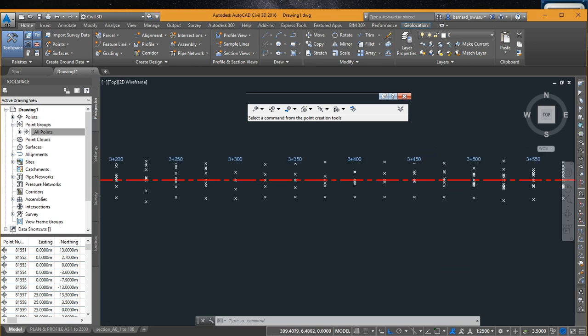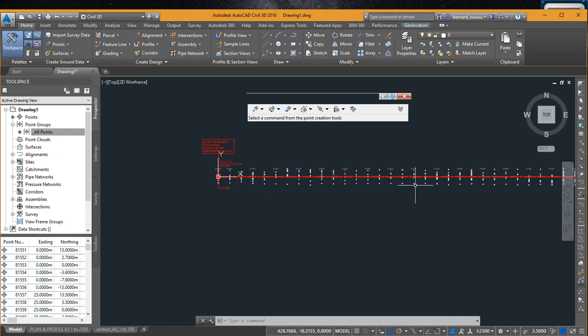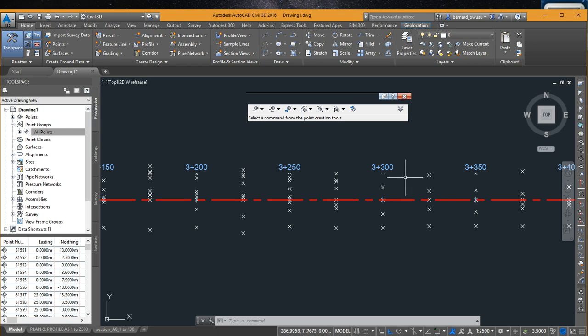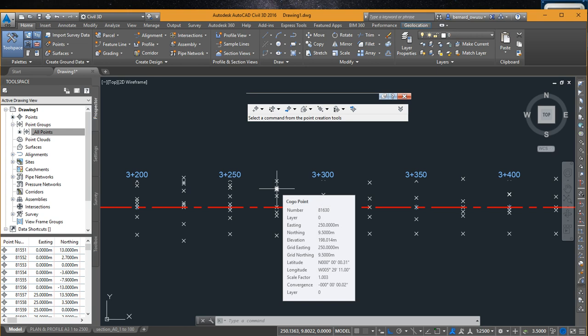Now, let's assume that we were sure of the center line that we drew. We've imported the chainage offset elevation into AutoCAD. The next time, maybe I want to give this data to somebody else. Once I have done it, I can export it as Easting, Northing, Elevation and give it to you, and for your importation you just import as normal import points. You will not need to define an alignment and import it.